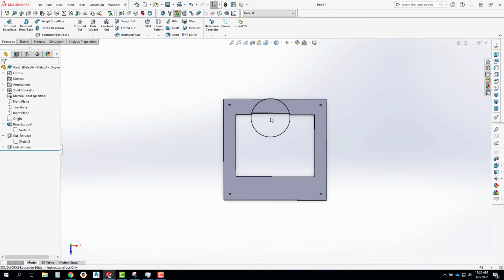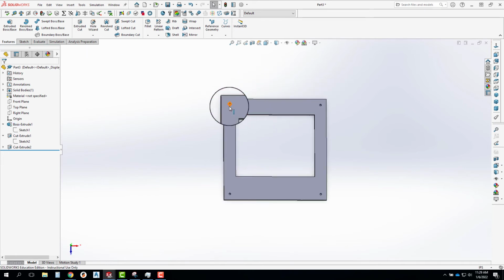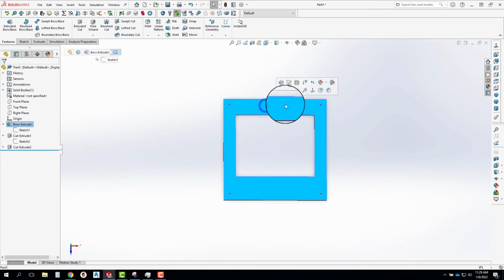Again, the most common ones you'll use will be vertical, horizontal, midpoint, coincident. Let's look at one other one that's related to circles. Let's say I wanted to add some counterbores to these through holes. So I wanted to create a little pocket, basically, that the screw head would be down inside instead of being up on the surface, because that'll let me use another handy one called Concentric.